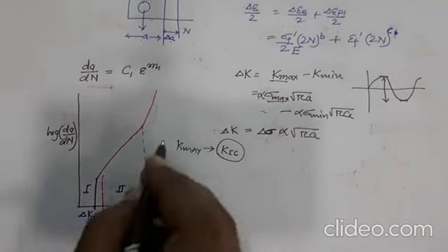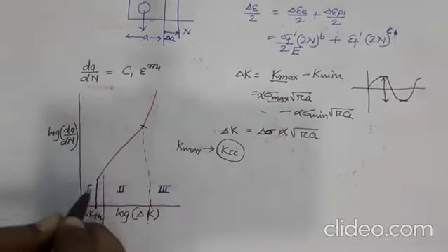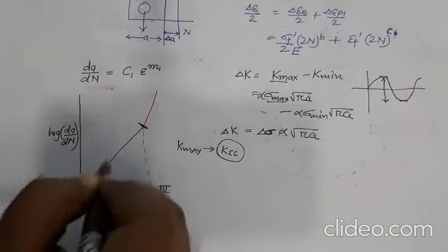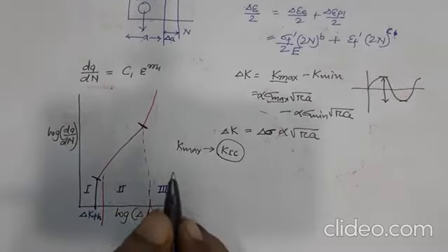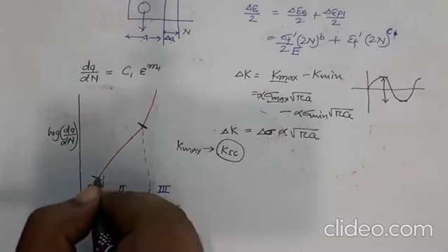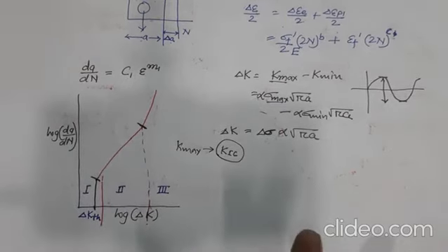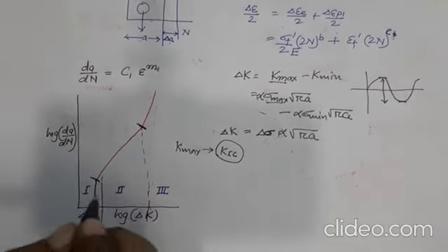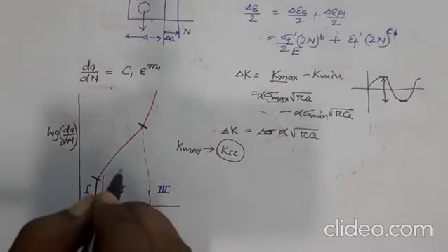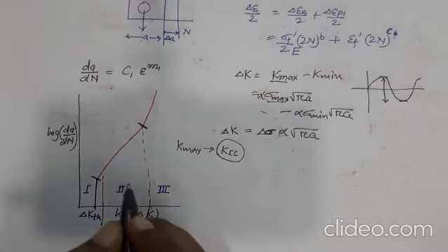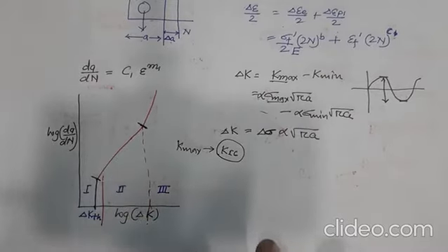Alright. So the most important part of this curve is this linear range, because here we can apply fail-safe design. So here we can predict the crack growth is not that fast that we cannot do anything. Even though there is a crack in the system and we know about that there is a crack, so maybe by ultrasonic testing we know that our pressure vessel is having some amount of crack, or our railway wheel is having some amount of crack, or the rail track is having some crack.